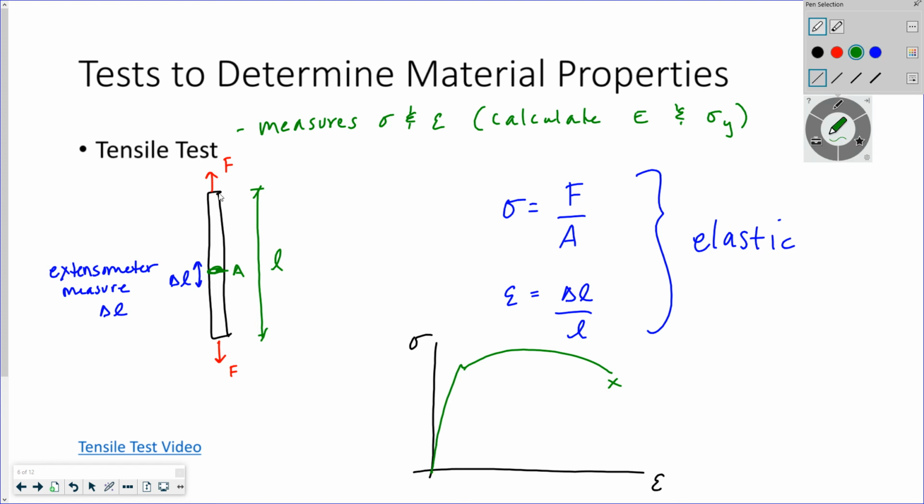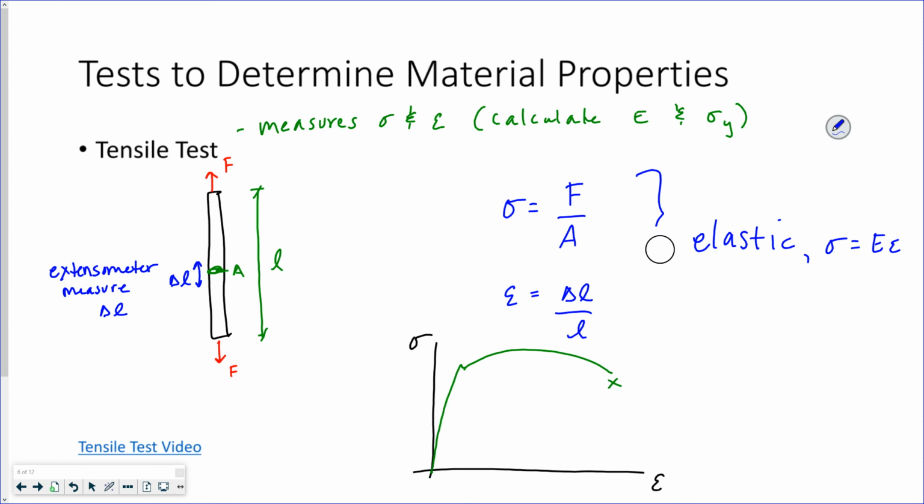Actually, I should say elastic stress equals E times strain. Because these are true no matter what. Although your area might decrease as you apply your tensile force due to necking.